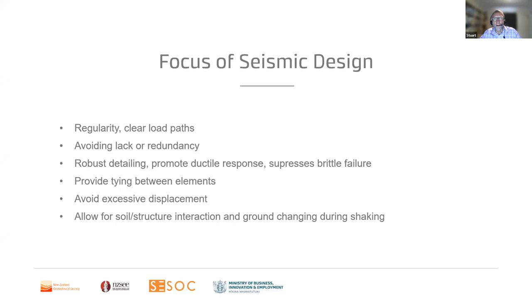Should be providing tying between elements, and that includes tying between foundation elements. Need to avoid excessive displacements and making sure that the displacements in the ground are well understood by the structural engineer and allowed for in the structural design. And we need to be allowing for soil structure interaction and ground changes during shaking, so liquefaction effects and the like. So it'll be that last bullet point that I'll be concentrating on in this presentation, but the document does talk through each of those points.